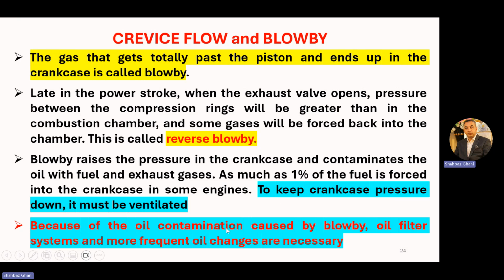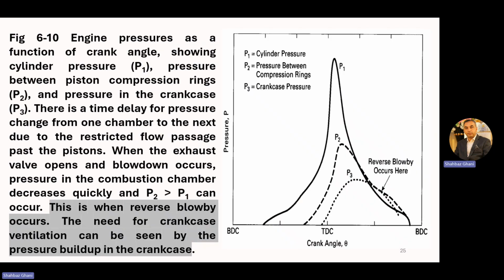Because of the oil contamination caused by blow-by, better oil filter systems and more frequent oil changes are necessary. So one of the reasons that oil loses its properties is the blow-by, and we have to replace the oil filter and the oil in the engine. Now, the last thing.